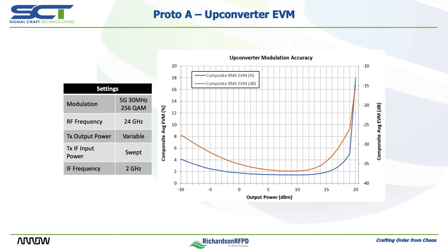Above this range, nonlinearities are beginning to degrade performance. It should be noted that no system optimization was performed prior to these tests. Tuning to improve I and Q balance, origin offset, and other system imperfections are expected to further improve this performance.